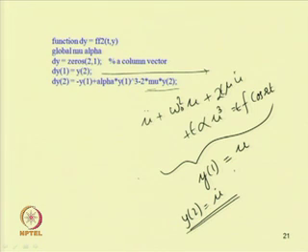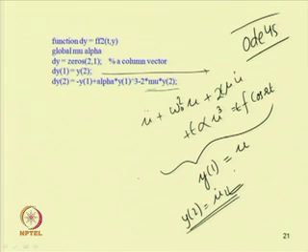In the RK4 method, or by using ODE45 in MATLAB, we can use the ODE45 function to find the response of the system. In that case the first equation is d y 1 equal to y 2. So u dot equal to y 2 can be written in this form, that is d y 1 equal to y 2. The second equation is for u double dot, so d y 2 represents u double dot.